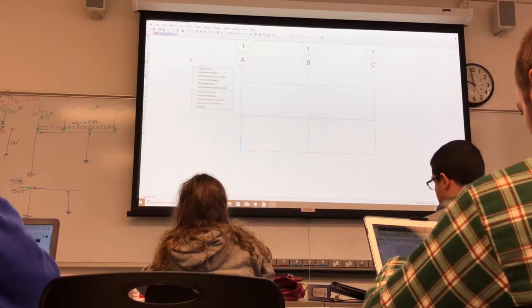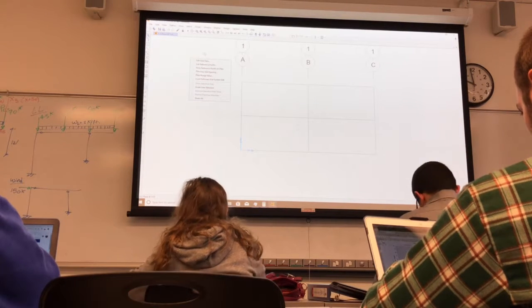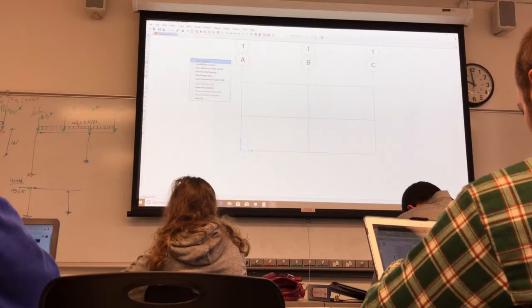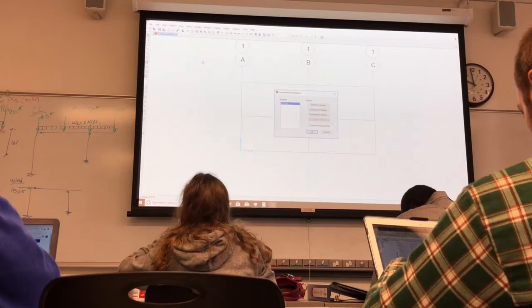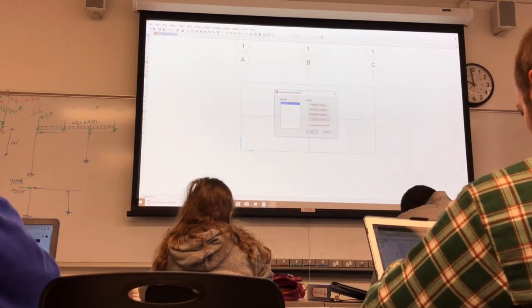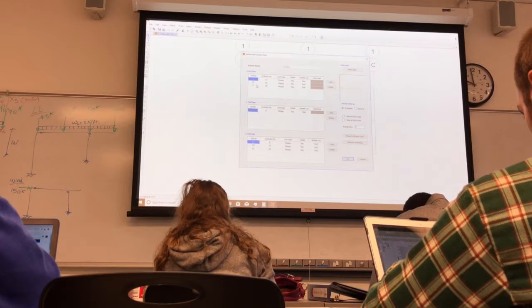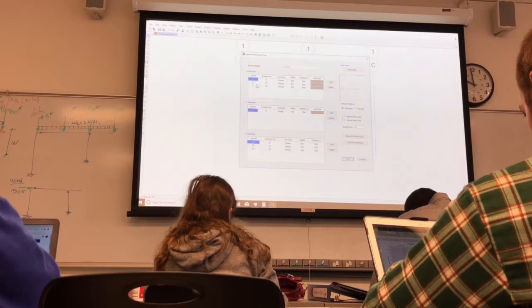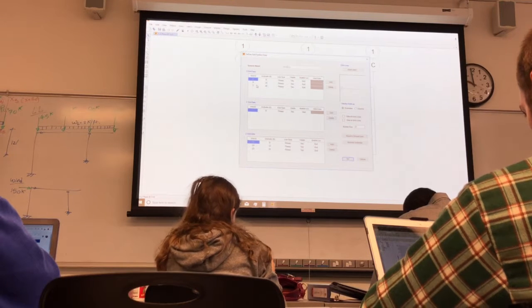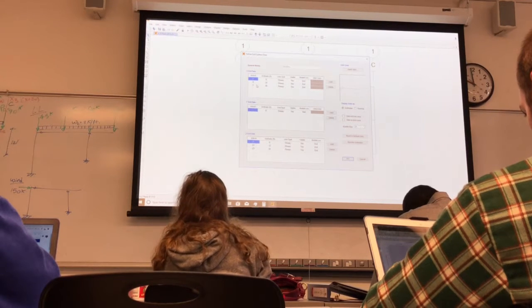So I can right click anywhere on the screen and go to Edit Grid Data. So I get the grid data, I click on Modify, I want to modify it, so it gives me the grids. So actually SAP used, instead of X1, grid A, B, and C. So that's just a name change.